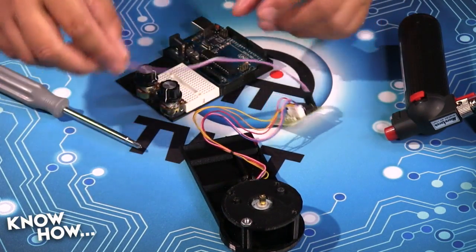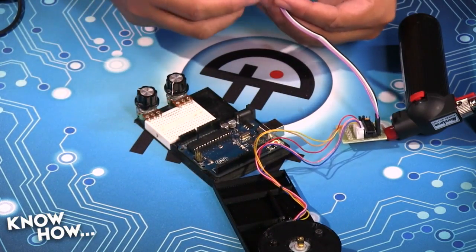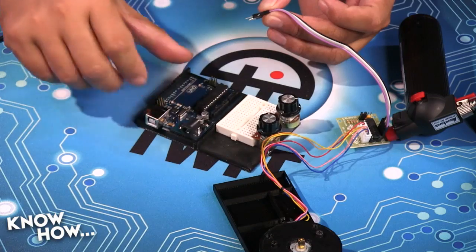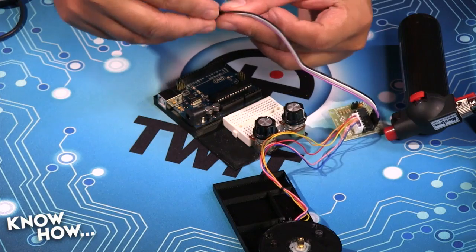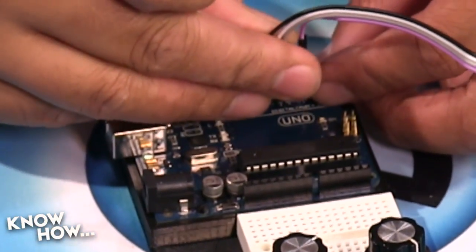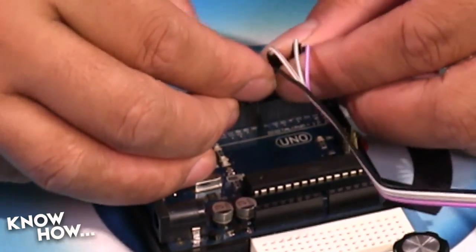Now on the other side, I need to connect these to 4 digital pins on the Arduino. I can't remember what I did in my programming, but I'm going to assume I used digital 4, 5, 6, and 7. So IN1 will be connected to 4, IN2 connected to 5, etc. I guess it doesn't really matter as long as you have it in the right order, because then we can change the number in the programming.